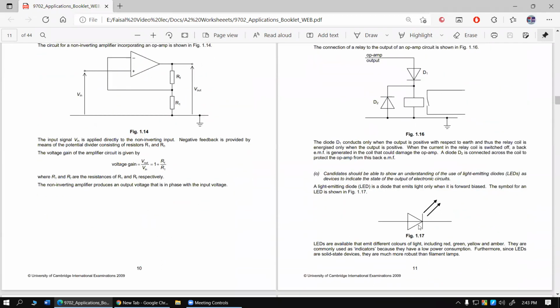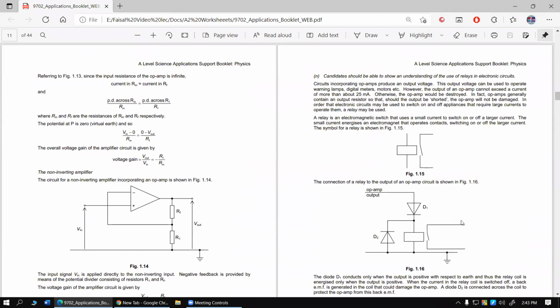So this was for the LED. I actually talked about the LED first. I forgot to discuss this. Coming back to over here, this whole thing is the circuit symbol for an electromagnetic relay switch. In this case, this rectangular box represents a solenoid, and this circuit will be activated by some current from some source, which in turn, if magnetized, will attract this switch, and this switch will be closed because of the attraction. This is always made with a soft iron switch.